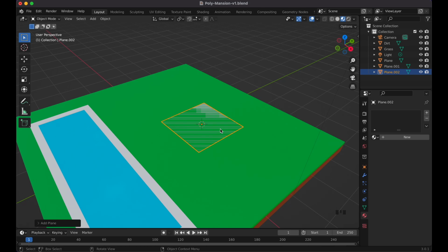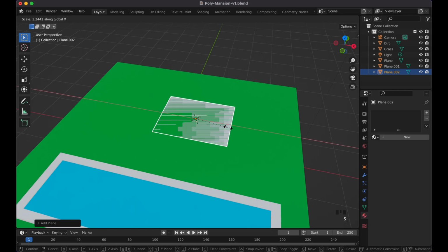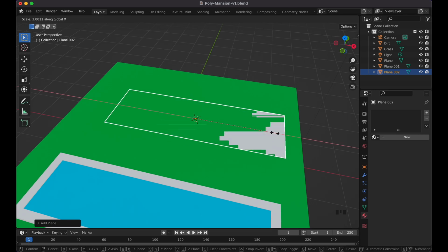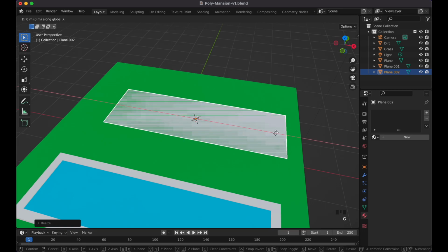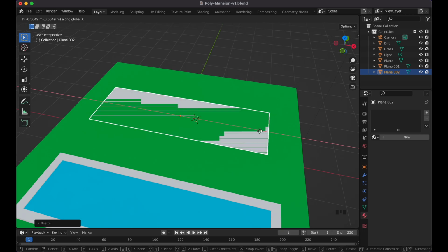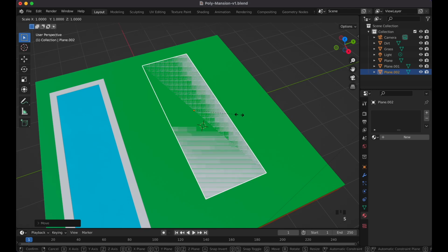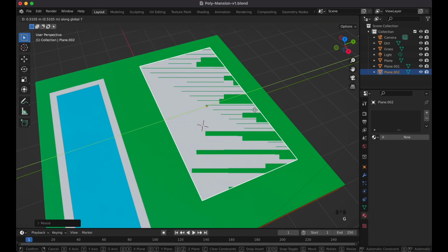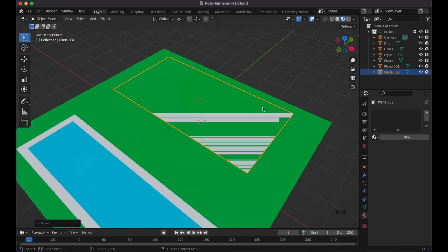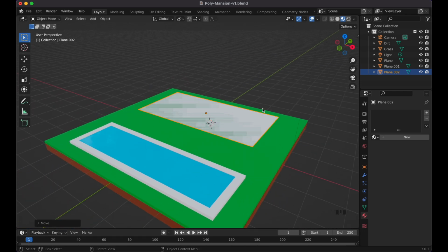Now this is going to be essentially like the house. So with design preferences, it doesn't really matter too much because I'm sure you can look at some references. But for simplicity's sake, I'm just going to make like a basic design. Nothing too crazy. And let's press G, X, move it like right here maybe. And then let's scale Y, so SY like this. And then I'm going to press GY to move it back a little bit like right here. And then we could technically scale this a little bit more on the X. But I mean, again, this is just design preference.